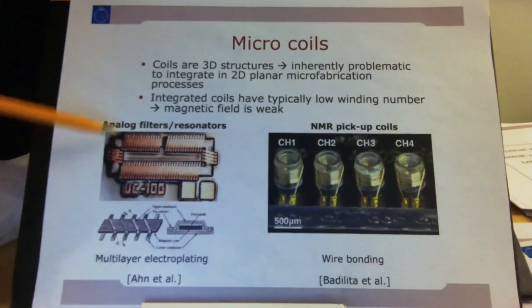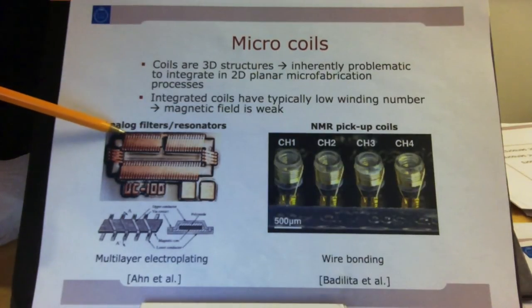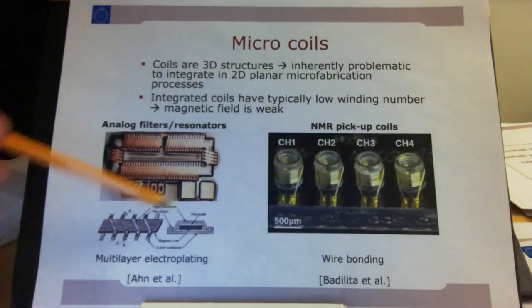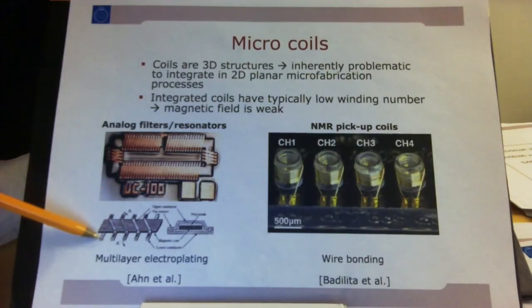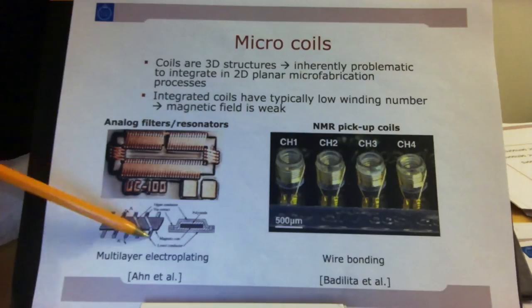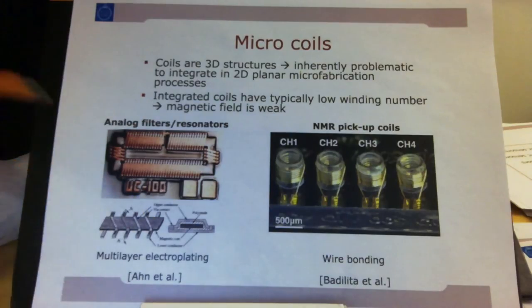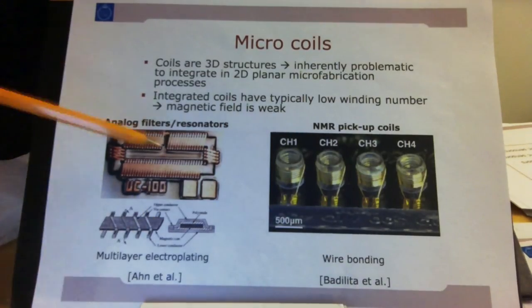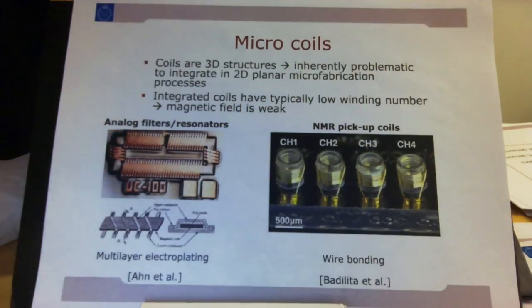Here you have a coil where it's basically a 3-layer structure. You have a bottom layer with one wire. Maybe you can see that even better in the cross-sectional view. You have a bottom with one wire, and then it goes through a connection to a top layer, and then back to the bottom. So you have below and up, and below and up, and that's how you build a coil, in a kind of 2D fashion. And here you can see how that looks.